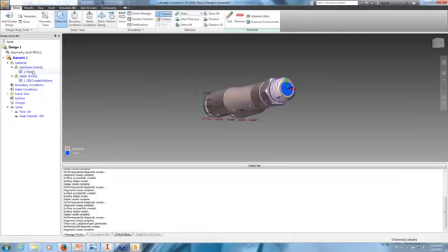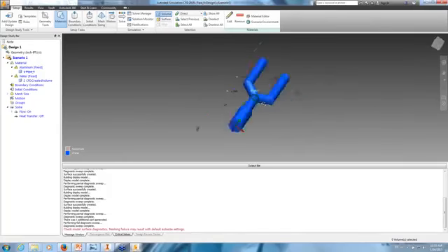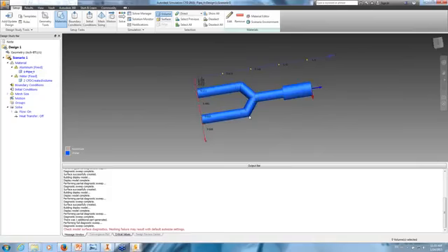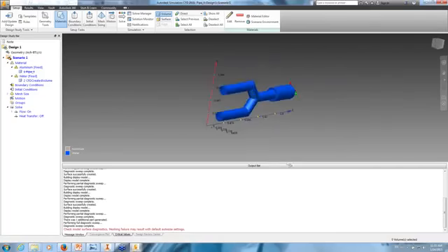And now I can select this guy here, right click, and suppress it. Not remove, suppress. Remove would remove the material, so you're going to have to redo it. What you want to do is suppress it, and you'll see it's crossed off. It doesn't hide it. I can hit the control key and my middle mouse wheel and hide it. And this is the actual volume that was generated by simulation CFD, by the software. So this is my flow domain.